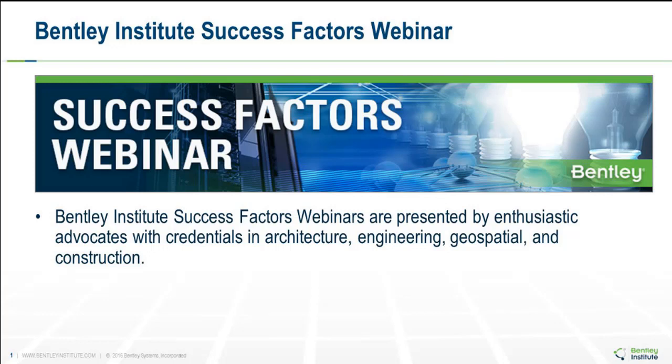Next question. Can reality capture be used for tasks other than visualization of a construction site and monitoring progress? Yes, it can be used. A typical example would be capturing an area. So you will get a 3D mesh of a green field. Then in another Bentley application, from this 3D mesh you can automatically extract the ground and use this terrain model as the underlying layer for your design.